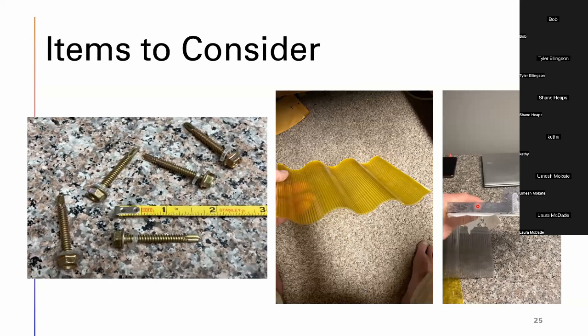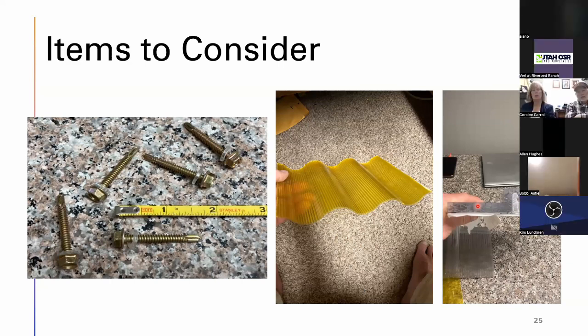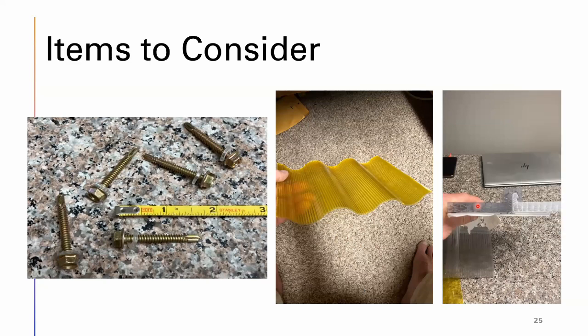Where we're at, we don't need a 90% transmissibility because it's a lot sunnier here. The intensity of the sun is a lot higher. So I should say most commercial growers are going to use the 2-layer polycarbonate. Now I deal with 4-layer. Why do I use 4-layer polycarbonate on my greenhouses?